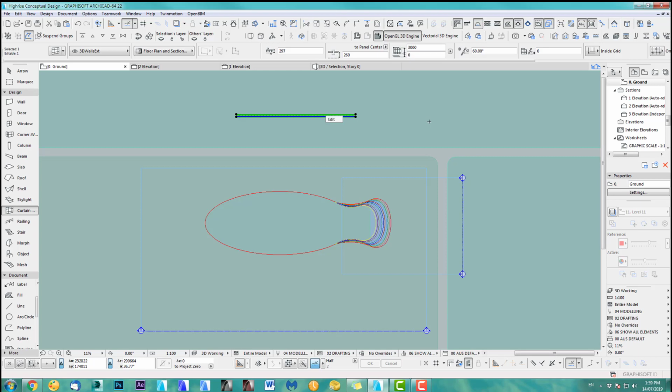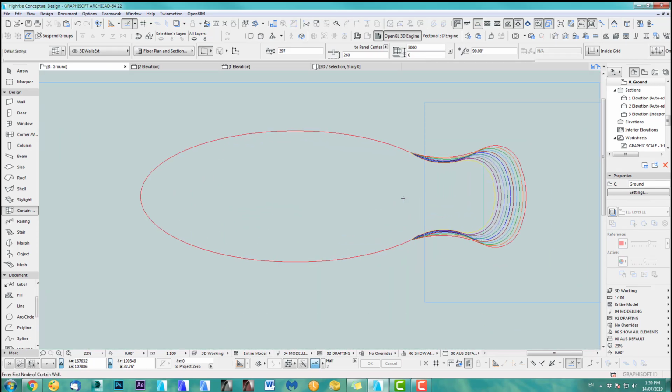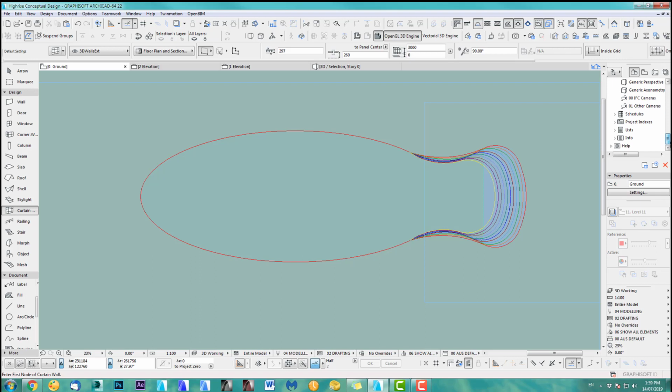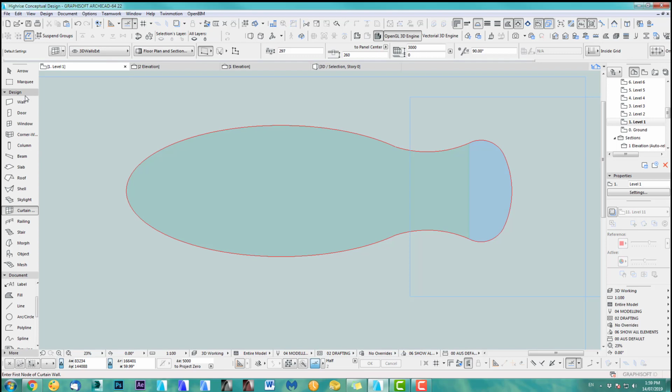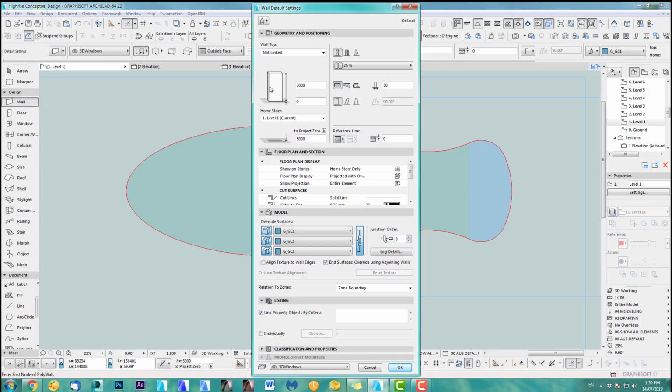So what we have to do is draw, as in one of my other tutorials, just walls. And I like to start not on the ground floor, because I want to make sure it's all fitting. I start on level 1. Okay, so level 1, I take a wall, and remember we got 3.6 from level to level. I made now the slab 600, that means I can do the wall 3000. Which in my case, you can see it's glass. So for now, glass 50, that's fine, and I put it on a window layer.